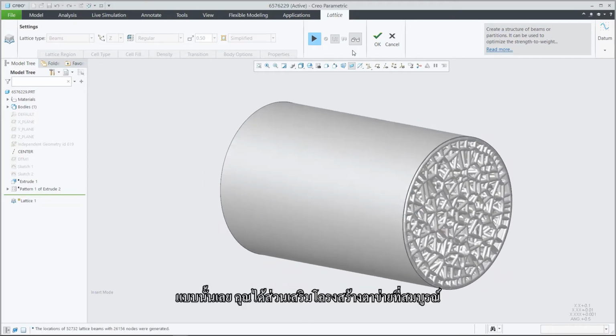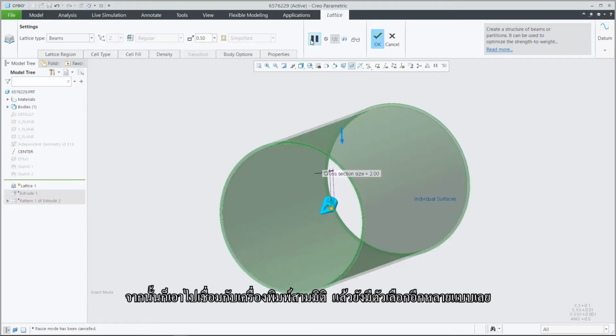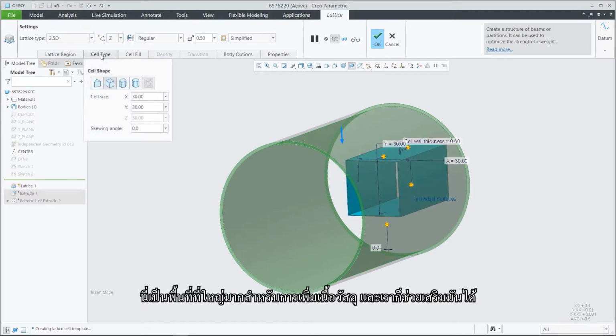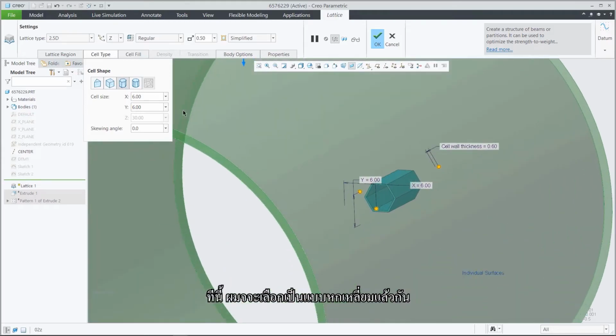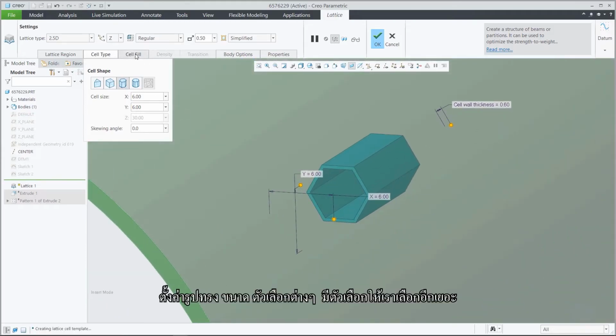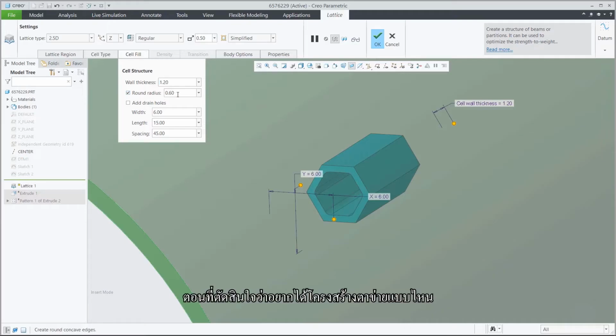Just like that, you have a full BREP designation of a lattice structure that you can then take to the 3D printer. And there's lots of different options there. This is a huge area of R&D for the additive world, and we can support them. So maybe something simple like a 2.5D lattice, I'm going to go for more of a hexagonal, if you will. Say set that shape, set the size, set the options. There's lots of different options you'll choose when determining how you want your lattice to look. In this case, I want to round off the inside radii, things like that.